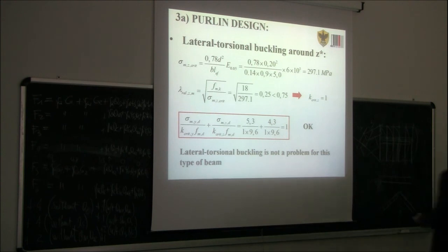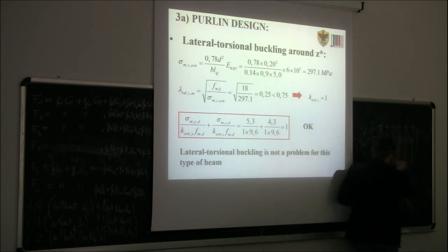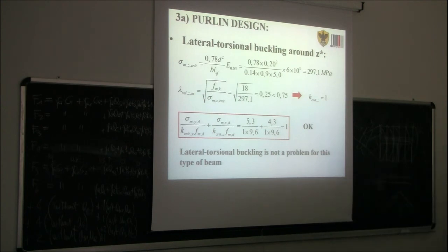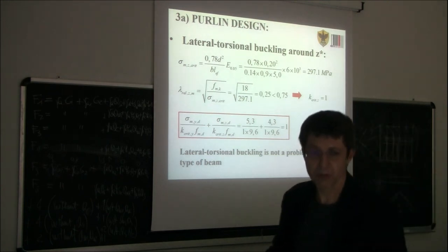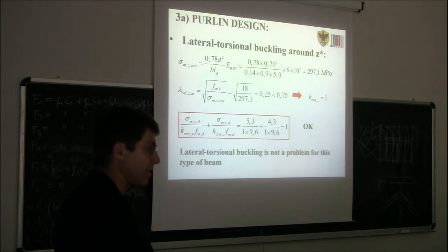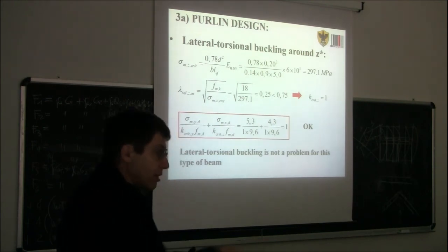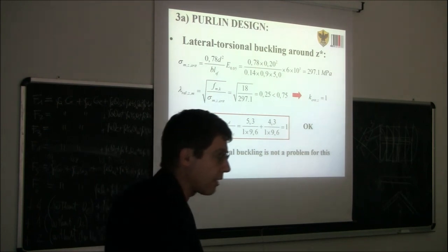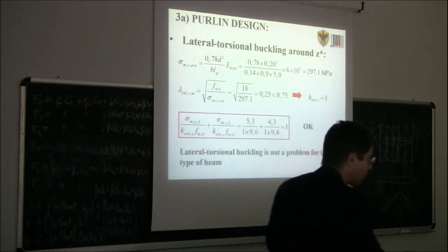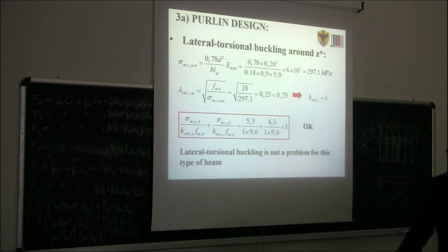Why? Because if you have a wider panel, for lateral torsional buckling of the beam we would need a distortion of the panel, which is very unlikely because the panel has an in-plane resistance. So the other option, if you want to make sure that you don't have any lateral displacement, is to replace the layer of narrow boards with a layer of plywood sheets or OSB sheets. So something which is not narrow and long, something which is wider and longer. These panels are usually 2.4 by 1.2. This could have been the option.